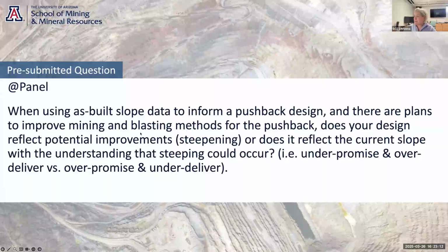When using as-built slope data to inform a pushback design, and there are plans to improve mining and blasting methods for the pushback, does your design reflect potential improvements, for example, steepening, or does it reflect the current slope with the understanding that steepening could occur? Essentially, they're asking, would you advise that you underpromise and overdeliver versus overpromising and underdelivering when it comes to planned improvements on your blasting and mining methods for future pushbacks?